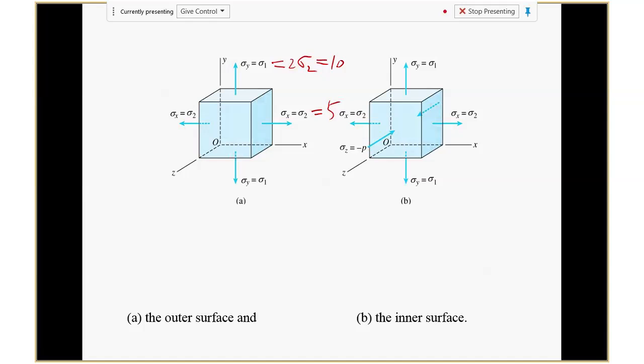So then if you look at the piece of that Coke can on the surface, this square is going to be under 10 in this direction, 5 in this direction. So longitudinal 5, circumferential 10. So that's the element we draw here. Now, what's the Mohr circle?